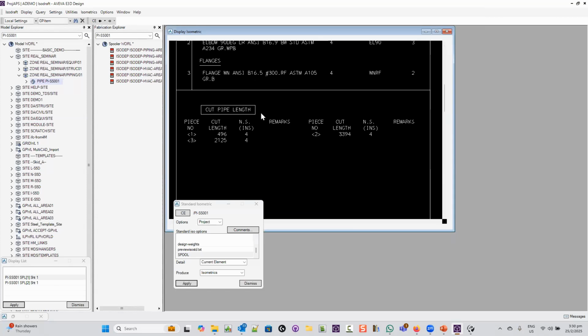Okay, another question. Good to have all the cutting length, but for steel pipe, I'm not sure anyone is interested in requesting the end configuration. For example, here you have a bevel end. You may have one piece of pipe where one end is a bevel end and the other end is a plain end for the socket weld.